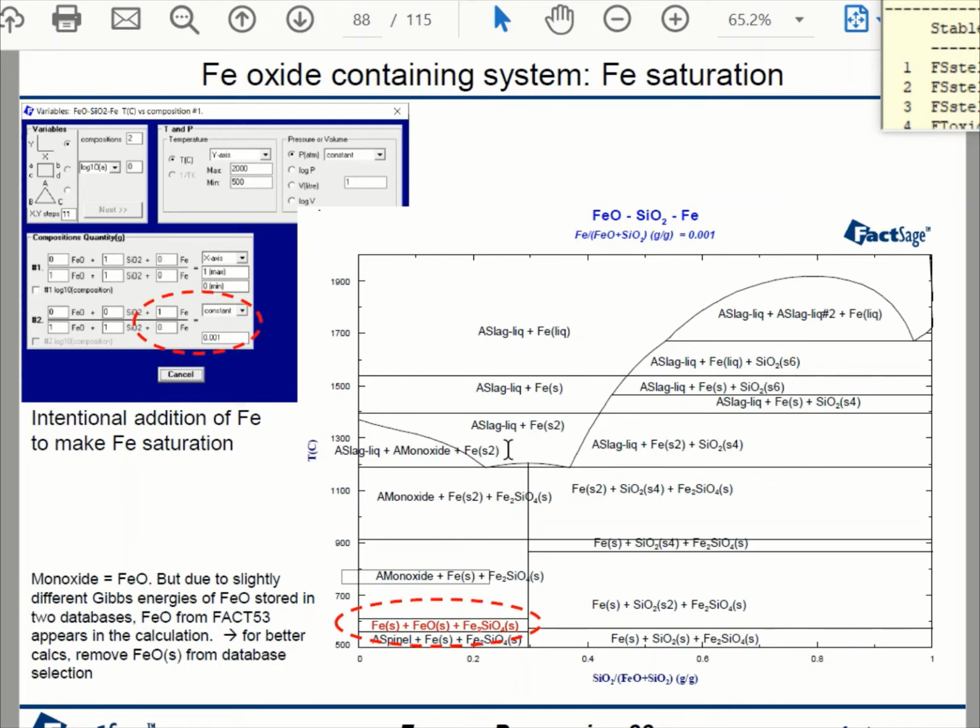And when you do the thermodynamic calculation for this kind of FeO-containing slag, you have to be a bit careful, because as we learned in the equilibrium program, iron oxide has multiple oxidation states: iron 2 plus and iron 3 plus. So if you don't properly set up the calculation for the amount of iron 2 plus and 3 plus, the program cannot actually run the calculation for you.